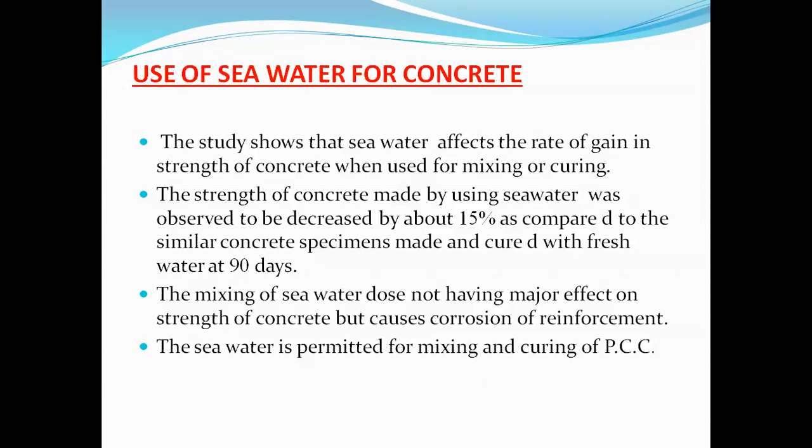So we use seawater at most for PCC work. That is point number 4. Seawater is permitted for mixing and curing of plain cement concrete, that is, concrete without steel.